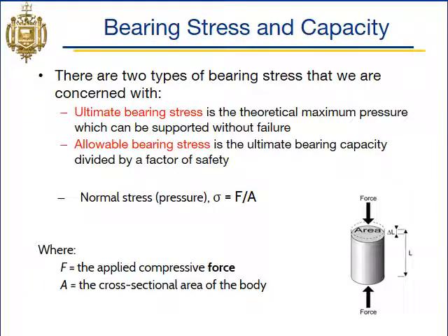So how do we calculate bearing capacity and bearing stress? Well, as the previous slide said, bearing stress is a normal stress. So our normal stress equation is what we'll use to calculate bearing stress. Sigma is equal to force divided by area, so sigma is our bearing stress.